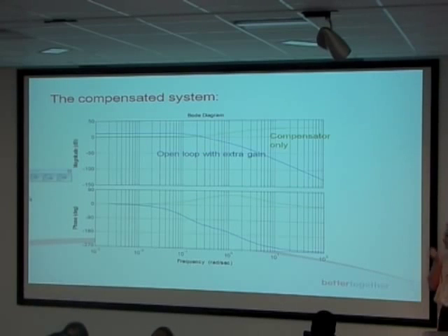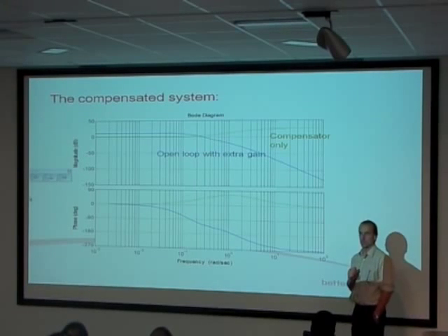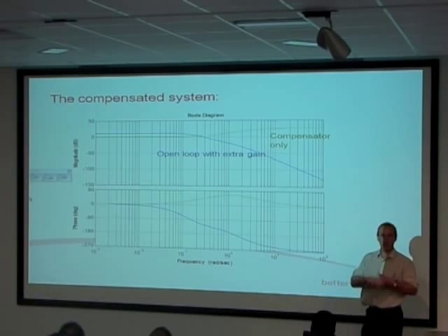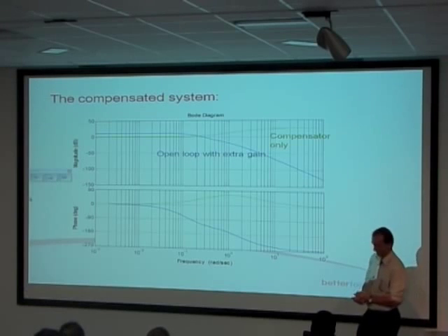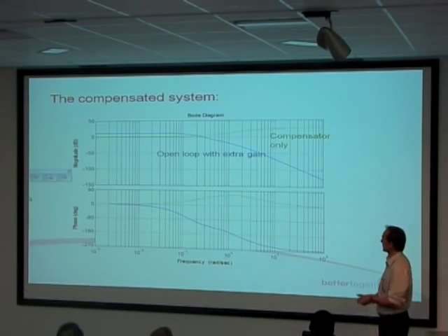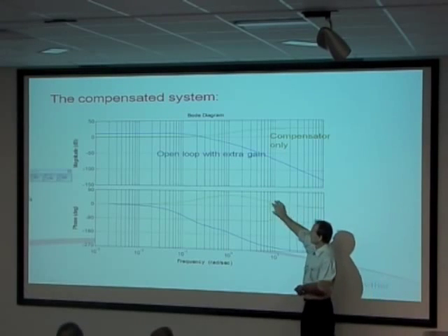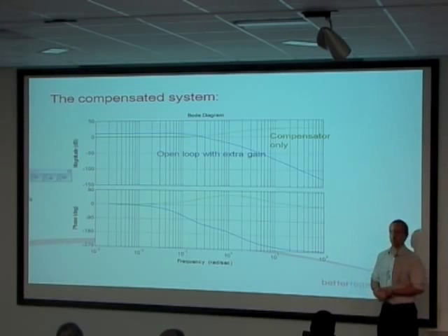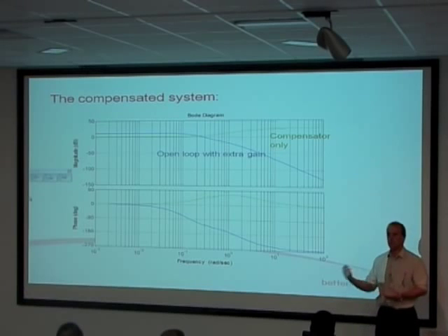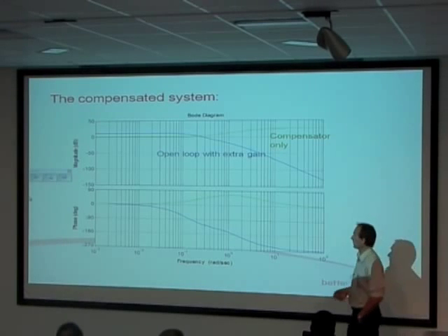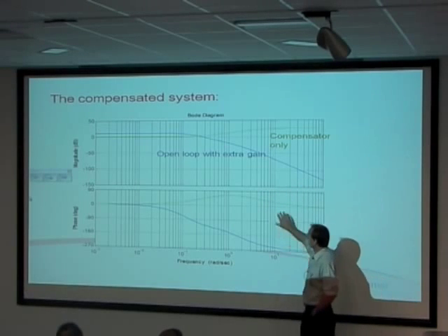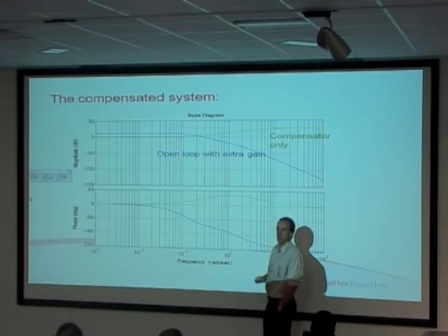Right, so let's see what the compensator looks like. The blue one is our system, which is the submersible and its actuator, the open loop transfer function. And through the magic design process I'm not telling you about, I've decided that my compensator is represented by this green line, that transfer function that was given a couple of slides ago. And you can see it's doing all of those things that a lead compensator should do. It's kicking up the amplitude a little bit, and it's providing a bump of positive phase angle.